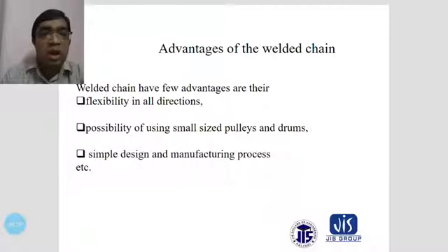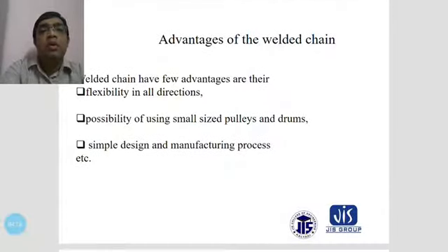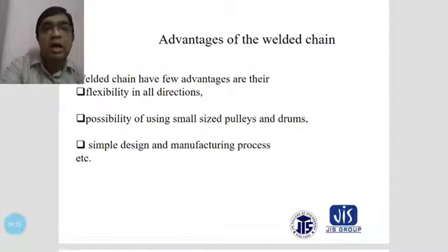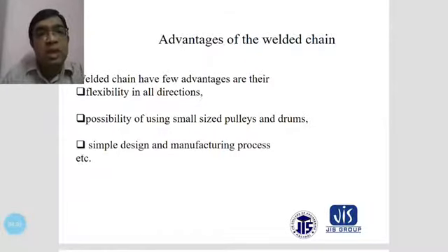And another thing, the advantages of welded chain. A few advantages are available with the welded chain. Welded chains have flexibility in all directions, like movement in all directions. There is no locking system here. And this movement is according to your choice; your materials can be moved in any direction. This is an advantage of the welded chain.